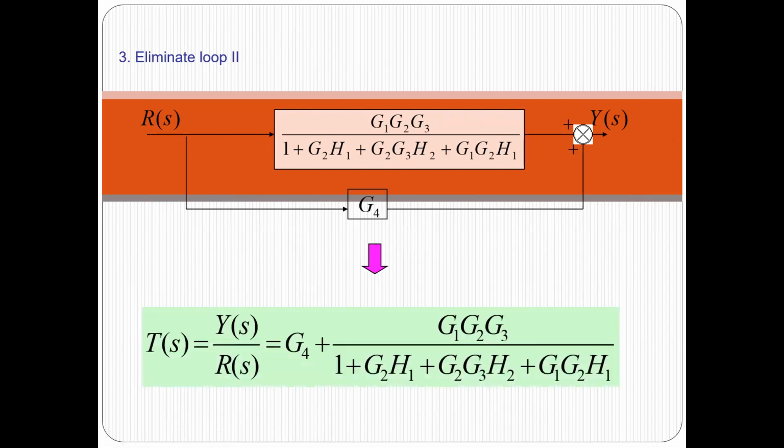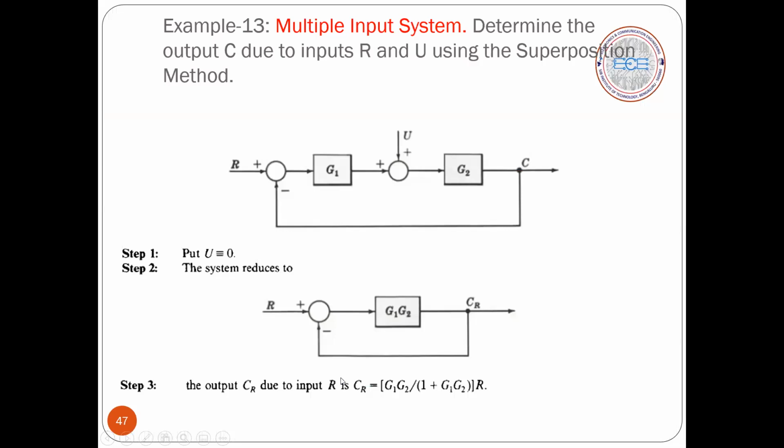Okay. So it is not a loop. It's not a loop. Very sorry. This is a forward block. I missed the direction. Very sorry. This is a forward block, and this is again a forward block, forward paths meeting at the summer. So these two are in parallel. We have to add. So we have done it here. Finally, this is the transfer function we have.